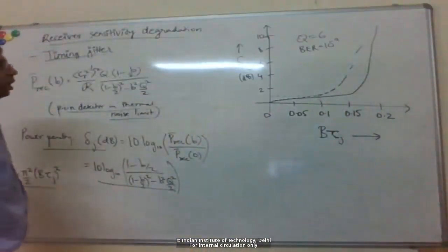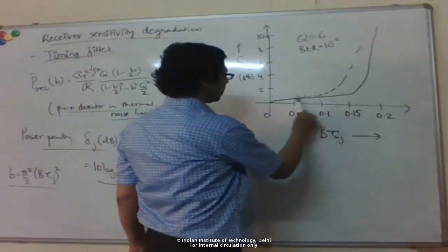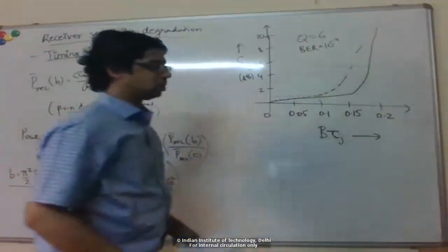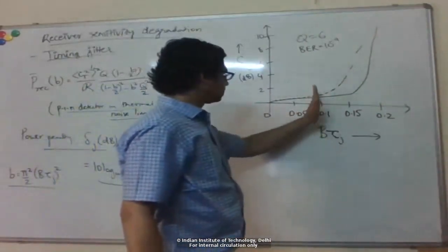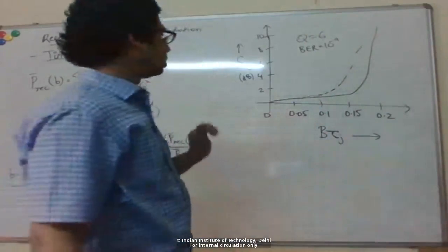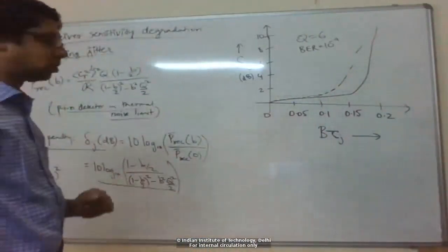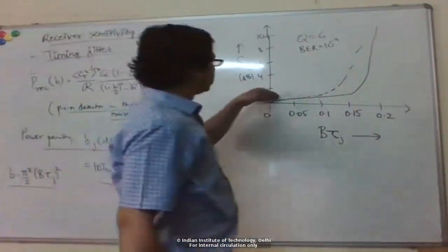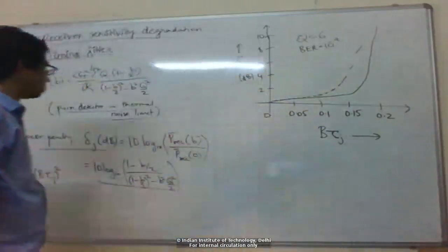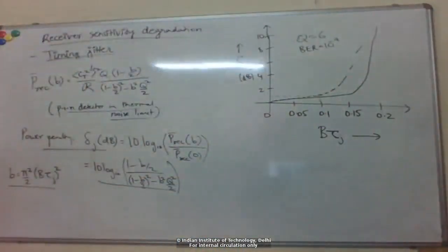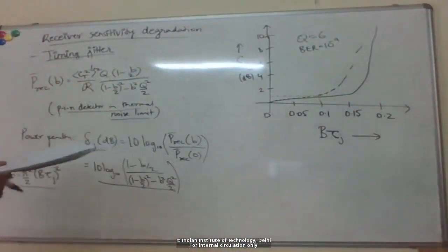Okay. But typically the effect is not that much if you're below 10% of the bit period. So this metric of the jitter being below 10% of the bit period works okay even if you have APDs, where shot noise is not negligible. It's just that it's a little bit higher and it starts shooting up early. Of course, the mathematical analysis will be a bit more complicated.